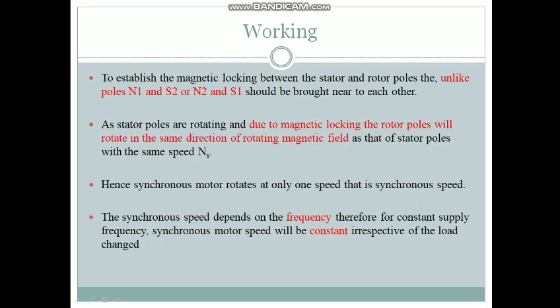The same thing is explained here. Therefore, a synchronous motor rotates at only one speed, that is the synchronous speed, and the synchronous speed depends on the frequency. Therefore, when we give a constant frequency, the synchronous motor will run at constant speed irrespective of the load. Whatever the load may be, the motor will run at synchronous speed only.